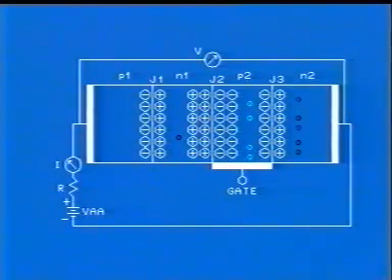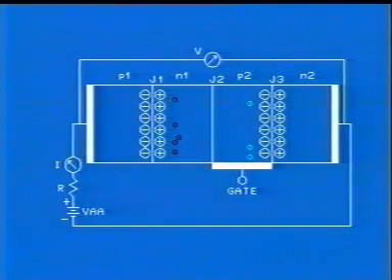This builds up a positive feedback, and a stage comes when concentration of holes in P2 and that of electrons in N1 becomes so high that the donor and acceptor atoms in the depletion layer at J2 are fully compensated. Thus, the depletion layer at J2 disappears. That is why the current through SCR increases and the voltage across it falls. The SCR turns on and there is a free flow of electrons and holes.